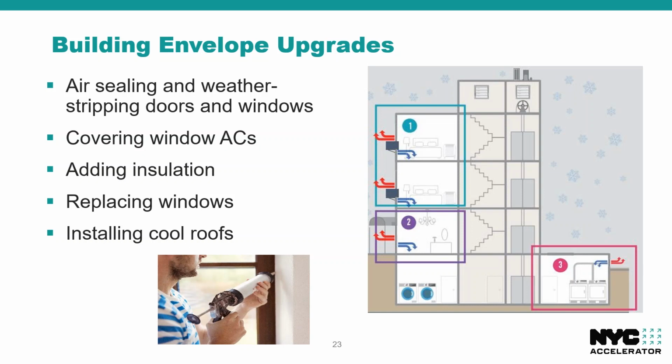Getting into some deeper retrofits, adding insulation to your buildings helps with your building's performance and comfort, as well as replacing older windows that have reached the end of their useful life. Energy Star rated windows save heating fuel by reducing conduction and infiltration heat losses.